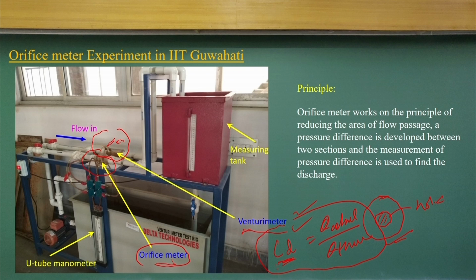So, that is the strength of Bernoulli's equation: we can easily incorporate experimental relationships into it, as compared to the Euler forms or other Navier-Stokes equation forms. Bernoulli's equation is very suitable and appropriate to incorporate any energy losses, or energy added to or taken out of fluid flow systems.